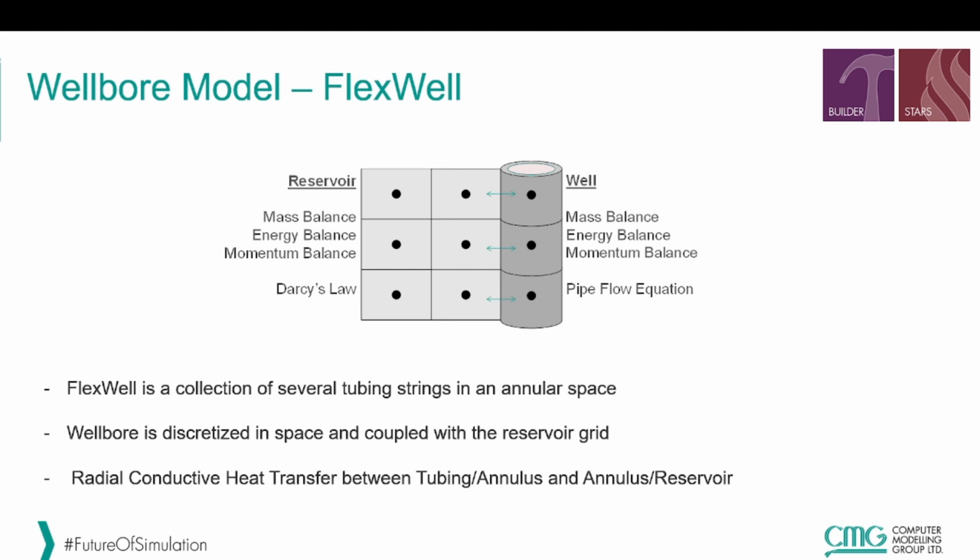The other option that will be activated by Builder for STARS will be the wellbore model in STARS, which is FlexWell, the flexible wellbore. FlexWell allows a collection of several tubing strings to be bundled up in an annular space in a fully coupled solution for the well. In the reservoir, we solve for mass, energy, momentum conservation equations, and for Darcy's law. In the discretized well, we will solve for the same conservation equations and for the pipe flow equation, and everything is done in a fully coupled way.